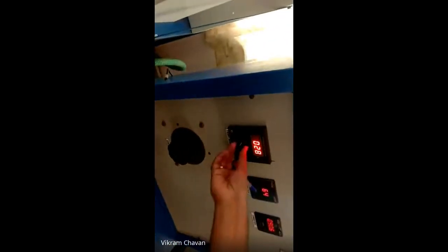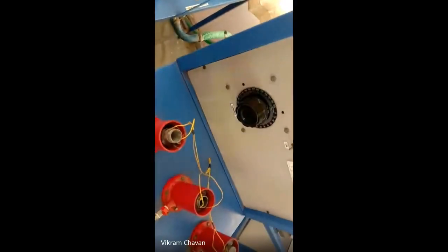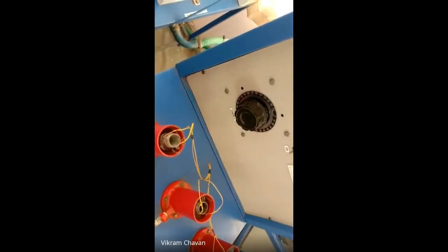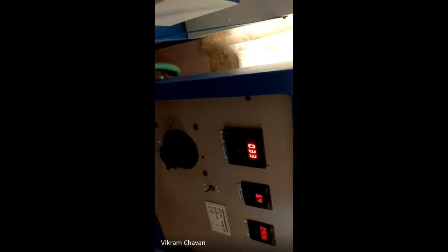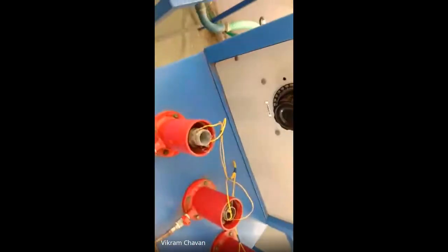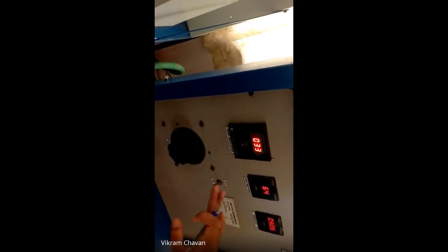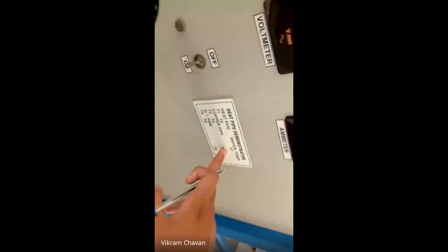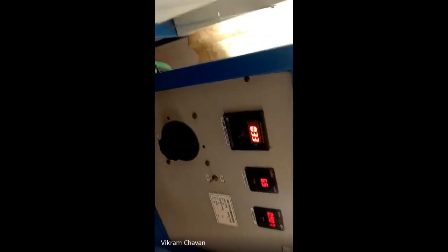Then T5. T5 is the bottom side temperature for the GI pipe, and it is equal to 55. Then T6 is the top side temperature for the GI pipe, and it is equal to 33. Now six temperatures we have taken on the surface. Now the water jacket temperature. Here you can see that T7 represents the water jacket temperature for the heat pipe. T7 we are getting 33.